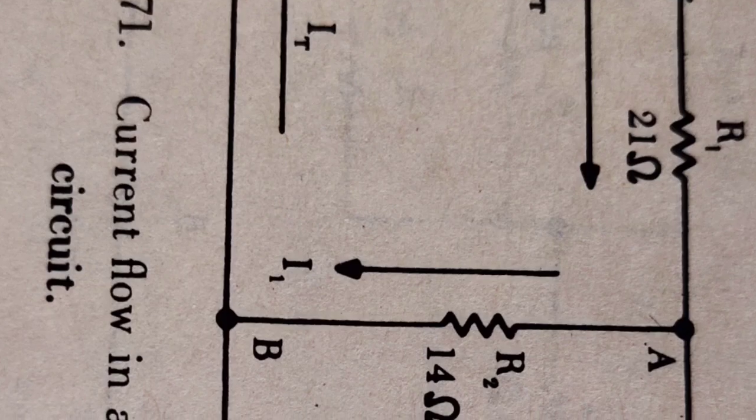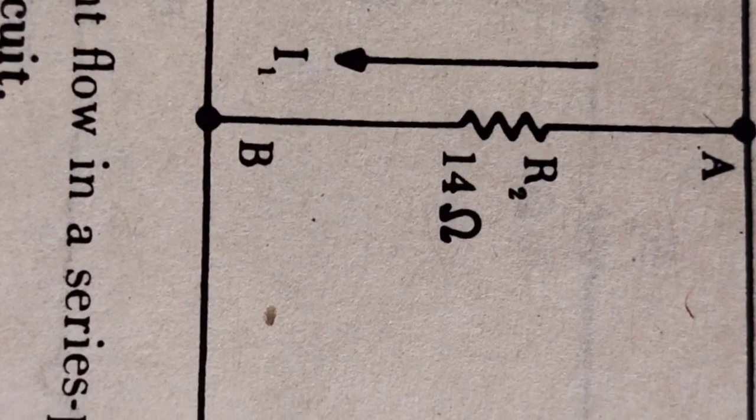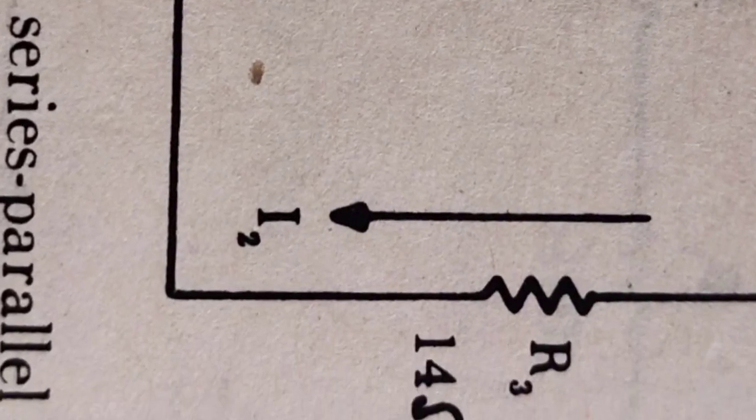The first series parallel circuit used is redrawn to discuss the behavior of current flow. Like the parallel circuit, the branch currents I1 and I2 cannot be established using the applied voltage, since R1 is in series with the parallel combination of R2 and R3. A portion of the applied voltage is dropped across R1. In order to find the branch currents, total resistance and total current must be found first.